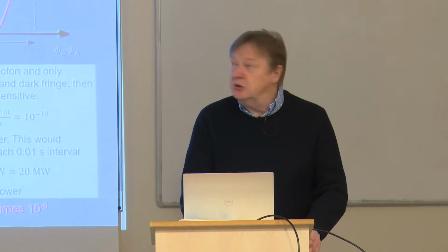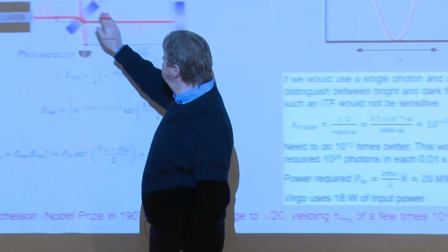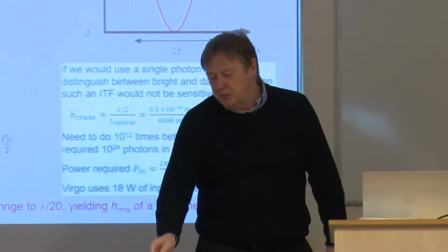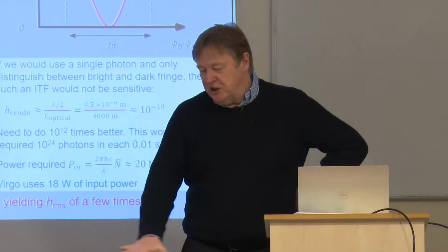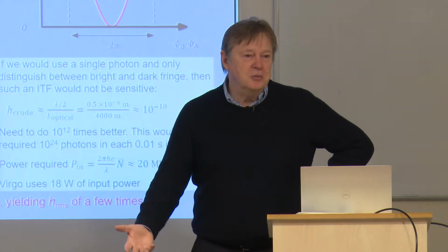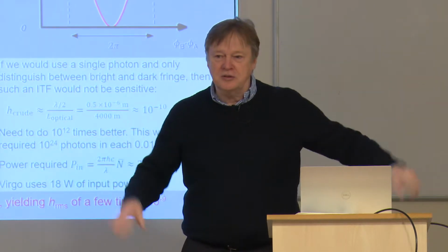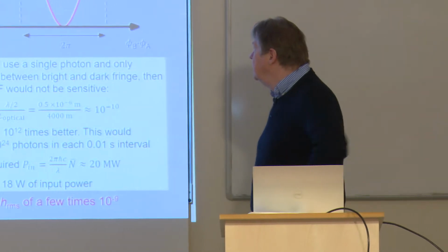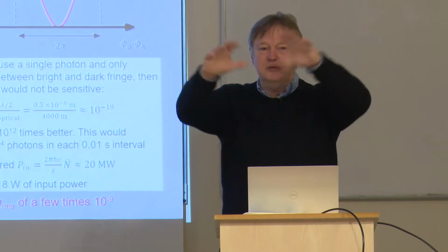Another thing that you need to do are these mirrors that you see here. Actually, all these main optical components, you cannot put them on the ground. If I were to put a sensor on the ground and measure the vibrations here, then typically this would move somewhere between a micron and a nanometer. Typically that would be the displacements, and you would have that everywhere on Earth. So you cannot put things simply on the floor, and you need to create something that looks like a free-falling object.